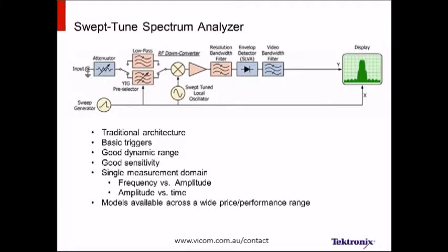This is important because very often when we're doing an EMI peak scan and we spot a frequency of interest, we'll actually put the spectrum analyzer in what we call zero span mode and look at the power versus time of the signal, trying to figure out what its periodicity is. The key thing there is that the power versus time measurement is seen through the eyes of the resolution bandwidth filter. So we're only going to see as wide as that resolution bandwidth filter can see.